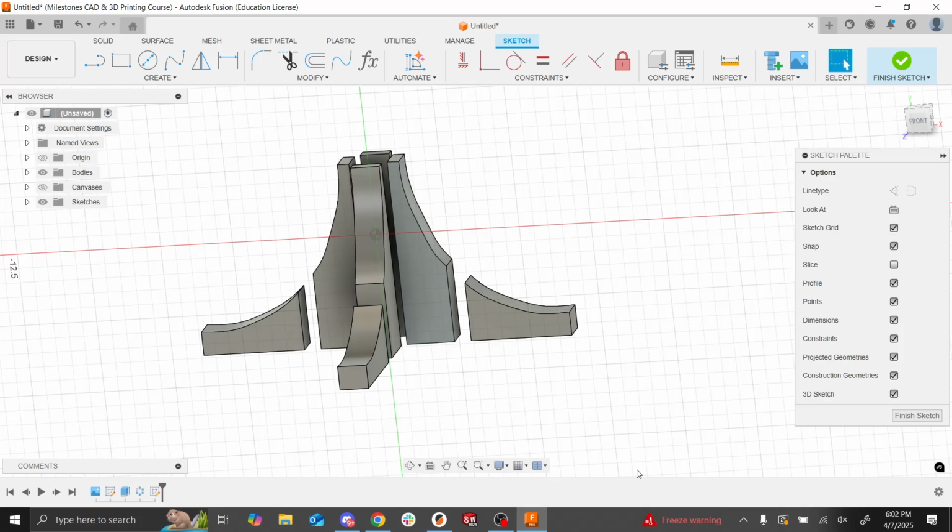Projections are pretty nice when you've created some geometry that you want to reference. In this case, I want to reference this edge here and maybe this one along with a couple over here. So we can use projections as a reference. If this were to ever change, the references will follow it, right?